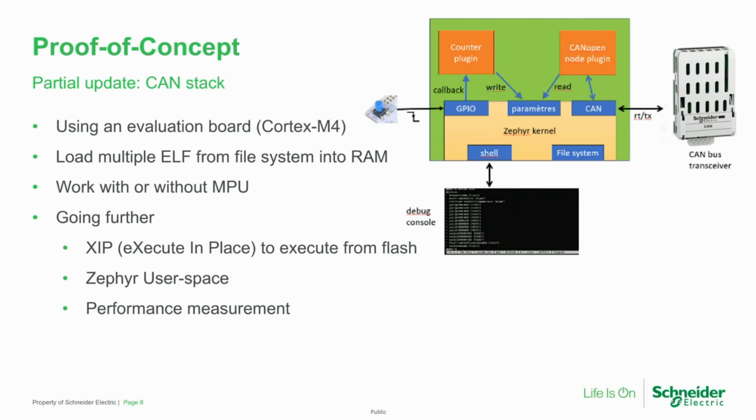Then we look at also the Zephyr user space. There you have a different constraint. I think you already talked about that. When you are in user space, you cannot say, okay, I want to call printk. Since you modify the code, you re-encode it to use printk, but then when you call it, you are not able to call printk because you are not allowed to call printk in the user space.